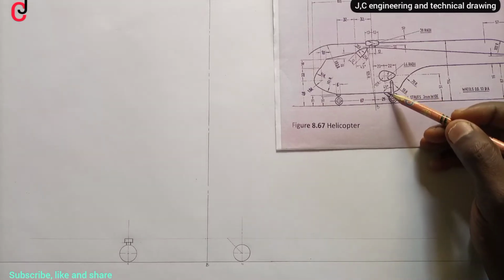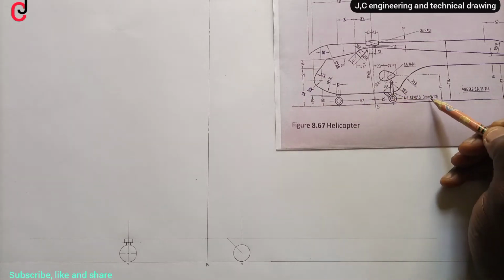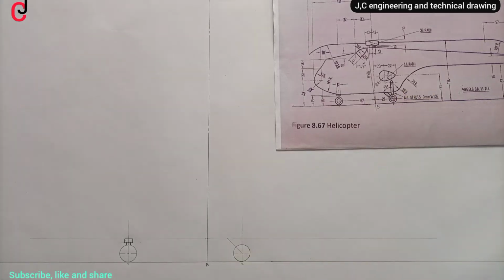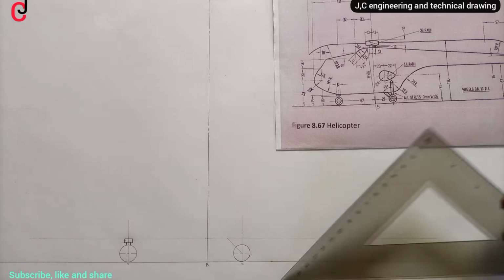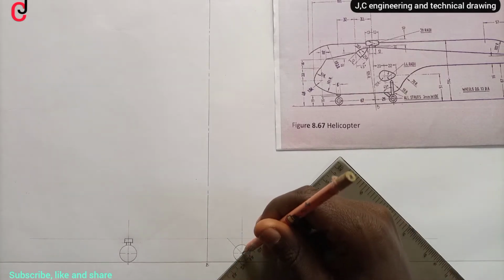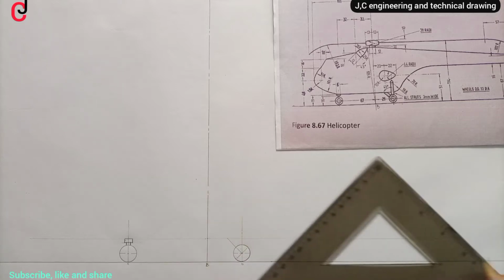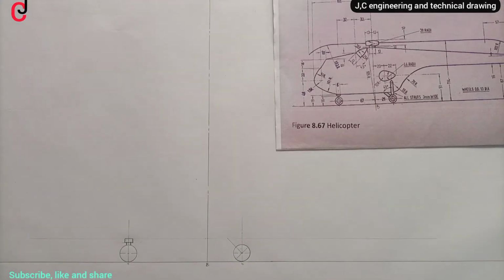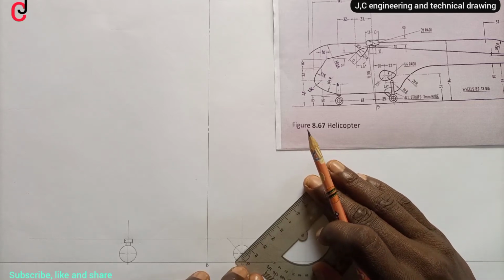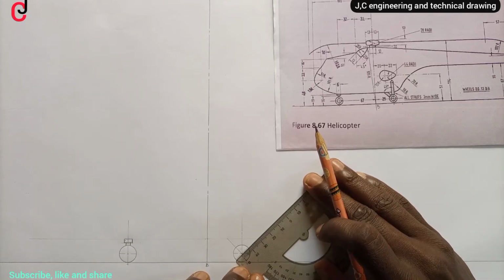And then we are told that at 45 degree the stud is 3 mm wide, so we'll place our 45 degree set square also this way, and then we'll measure 1.5 mm to our left, 1.5 mm to our right.